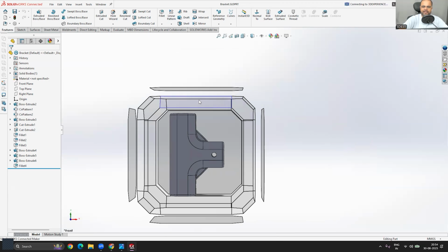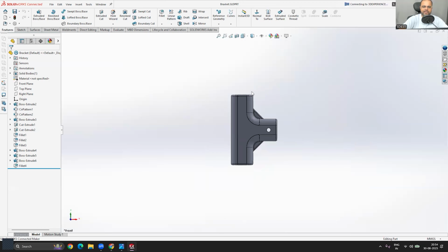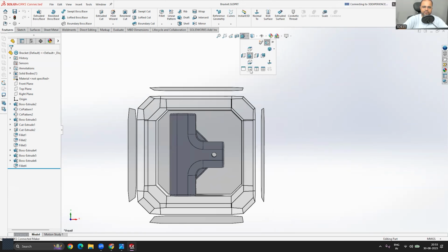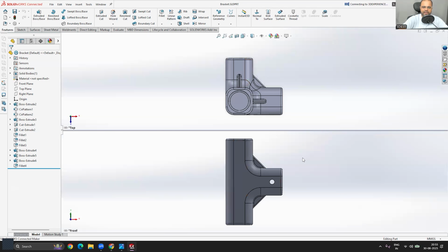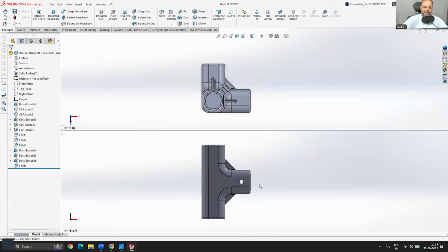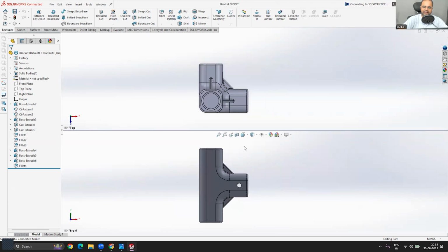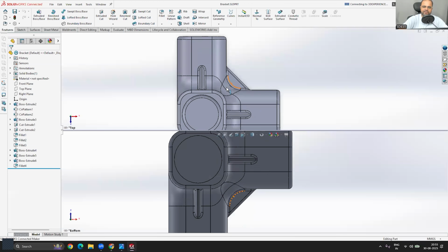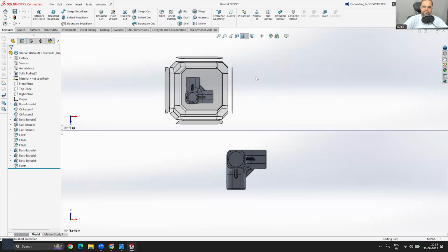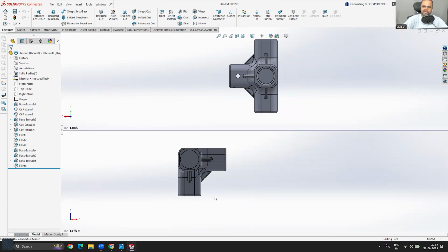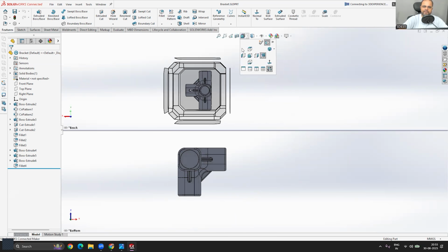Like right now we are active in a single viewport, right? The canvas you can see is just a single one. So that's why we are active in a single viewport. If you want to split that into multiple, you can click on it, and now you can see in one viewport we are seeing the body as something like this, and in the other viewport we are seeing the body as something like this. So in different viewports we can apply different view settings. You can see that. Here, let's apply this kind of view. So in different viewports, we can apply different settings.